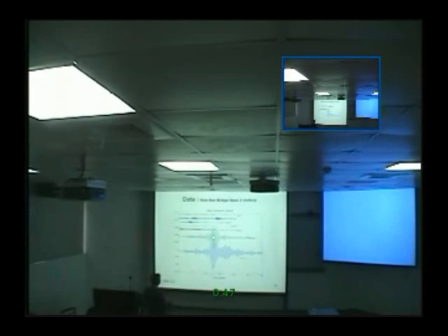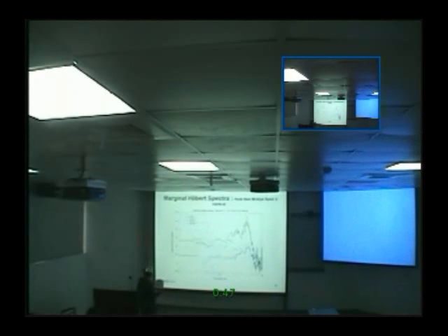And even under this load, when you compare to the other cars like 14 and whatever, you find that 14 is this one. The peak is less than the noise level, but the frequencies are perfectly aligned. That means this bridge, even under the heaviest load, still behaves linear. So this span has absolutely no problem.